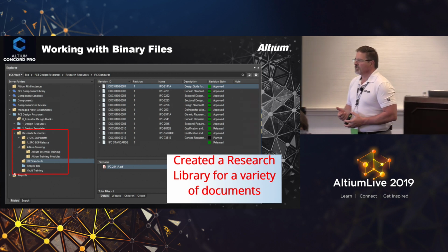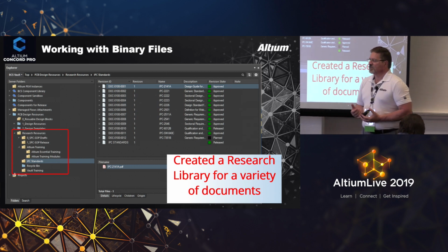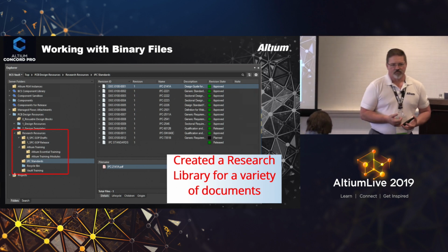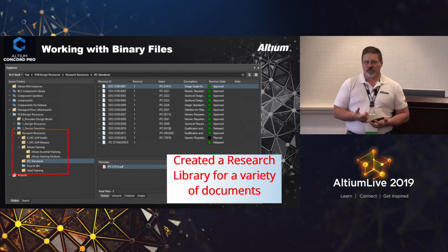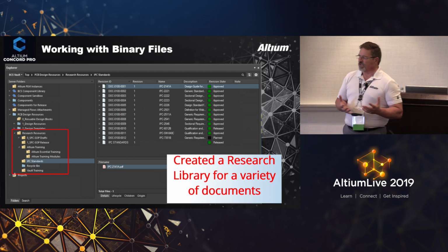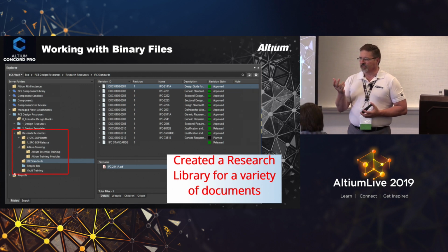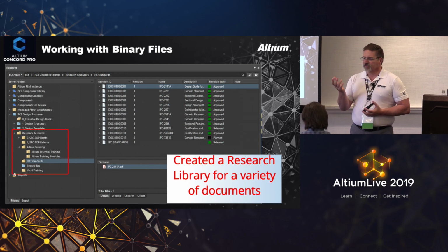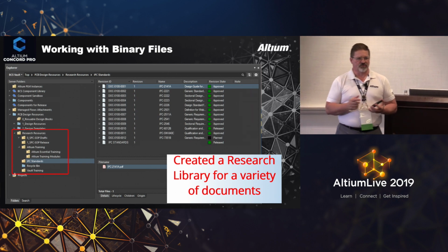Step models, right? You get a step file and you place it in the component library. Okay. We've had it used, everything on the layout. Because you're not changing your footprint. If you put the insulator on, the footprint for that TO220 package is still going to be the same. So what we've done is we've actually created an entire library of mechanical components: screws,